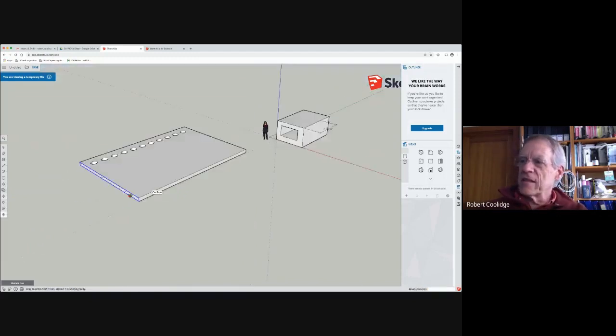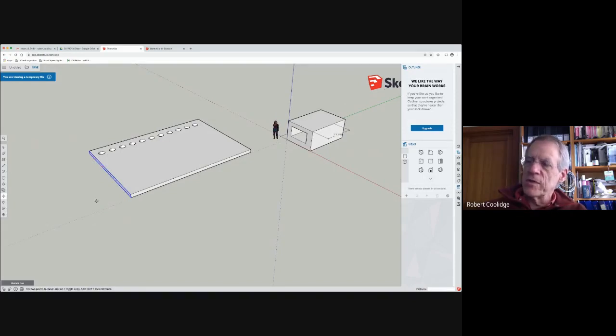One of the advantages to doing noun-verb is that you don't have to point to the thing in order to move it. So for example, if I want to move this surface by the length of this edge of that object over there, I've pre-selected it, right? I can go over here, do my first click on this corner and drag to this corner. And I've moved this face by exactly 16 feet, the distance of that edge over there. So I've used up to two other reference points to do that move. That's something I do quite commonly.